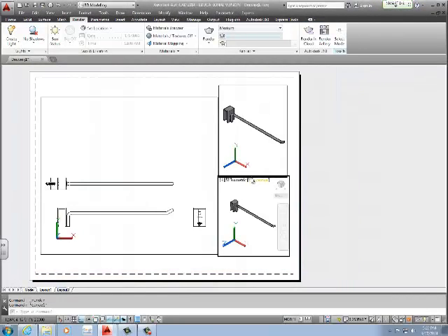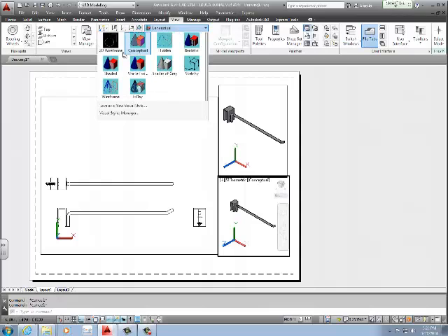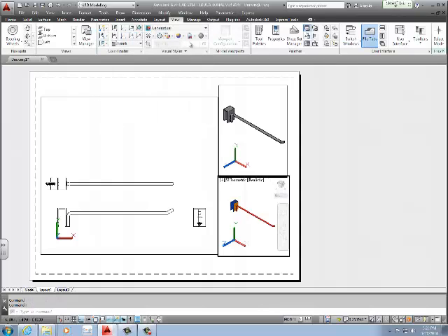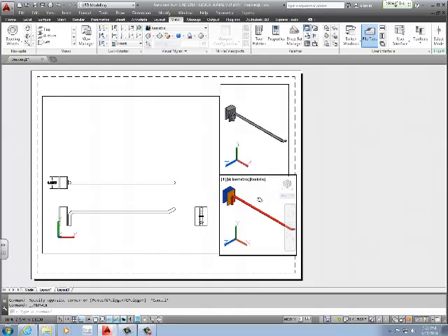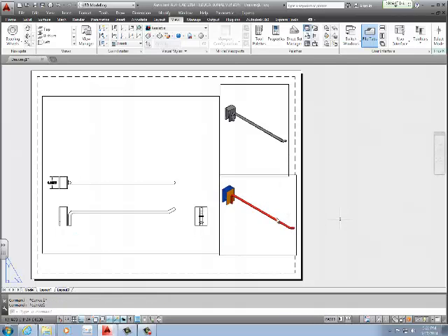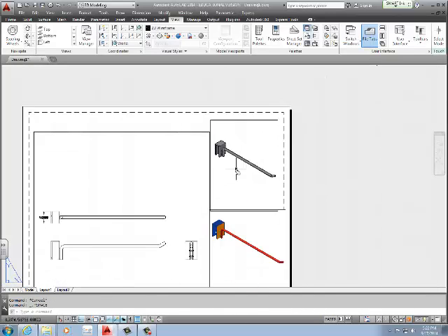It's not going to let me, so I have to go to a visual view of realistic, because when we do the sweep command, we can select the circle. And there's a realistic style, which places the right material on it. It's not completely rendered. I think we are done with the basic 2D drawing. You can always go back to add an additional rendered view. But for now, we're going to leave it as is, and we're going to go into 3D modeling. If you're not in 3D modeling, do so now.